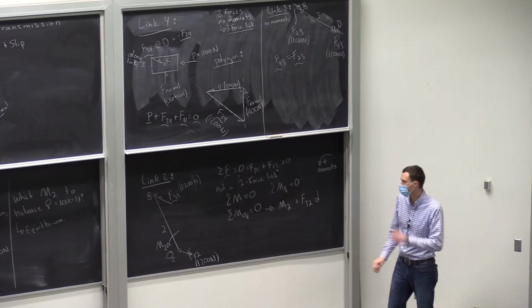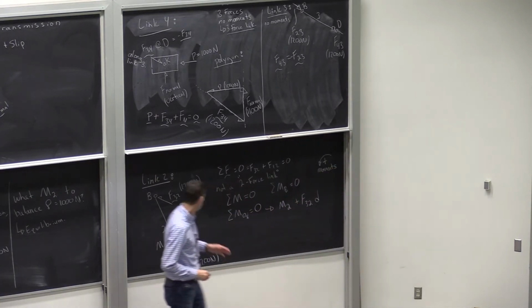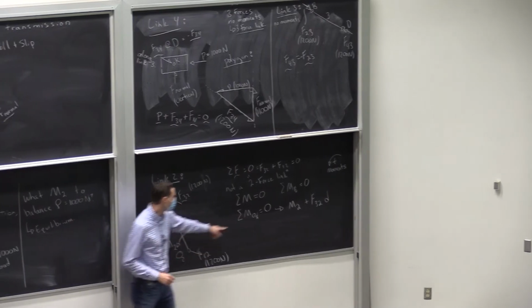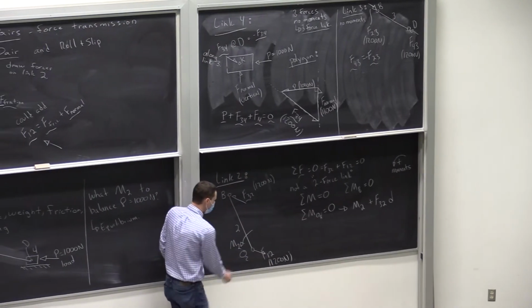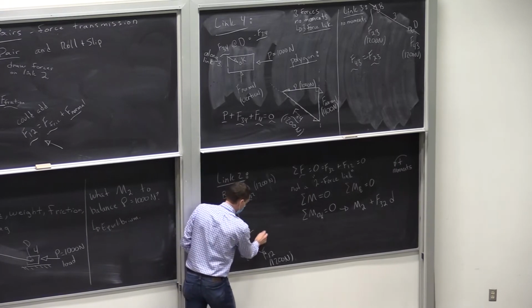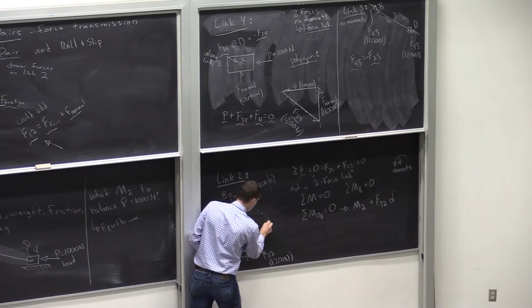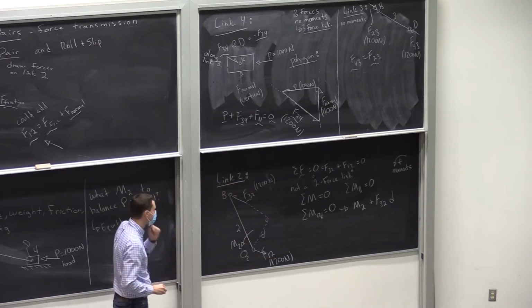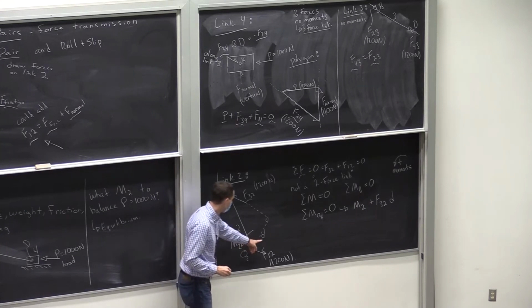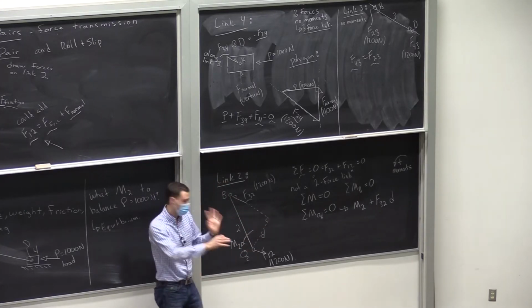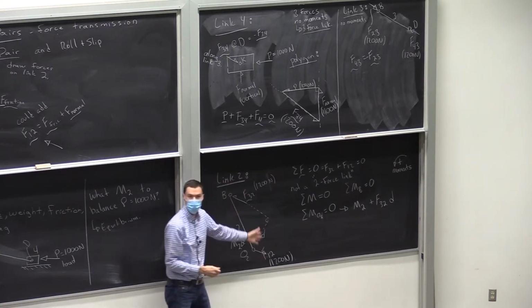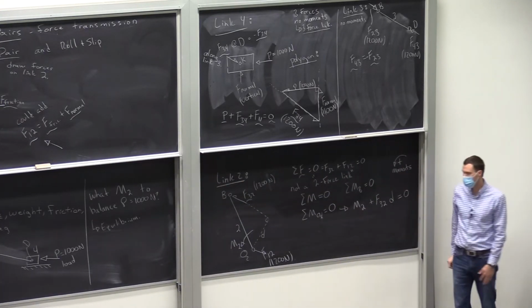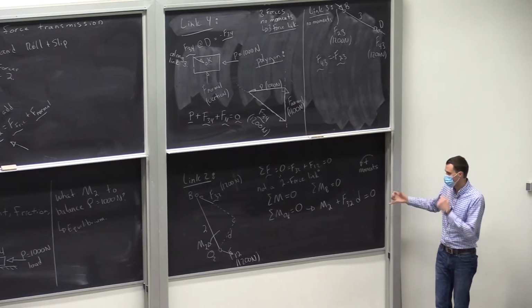And we did this last time. The moment arm needs to be the distance between our force and the point about which we're summing. So you can't do distance this way. It has to be perpendicular distance. That distance there, that's our moment arm. So you lay this out accurately on your page, and you measure D. And you can plug that in here. This is our sum of moments, and we sum to 0. So what we're solving for is M2.